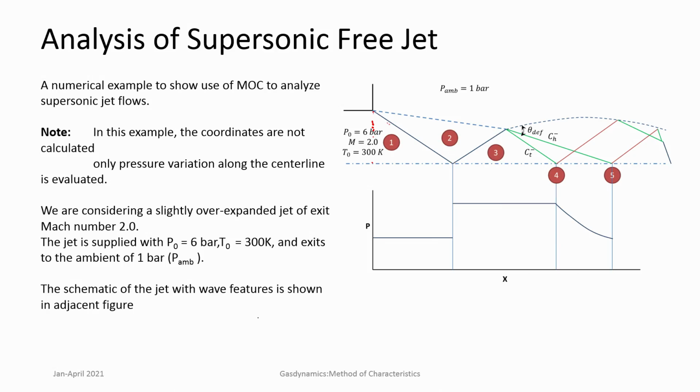Now, this oblique shock wave will come to the center line. At the center line, of course, the flow has to maintain theta equal to 0 condition. In order to ensure that that happens, because if you consider a streamline here, this streamline is deflected towards the flow, but at this particular region the flow has to be parallel again to the x axis. Therefore, another shock develops. As a consequence of two shocks, you get region 3 which has much higher pressure.